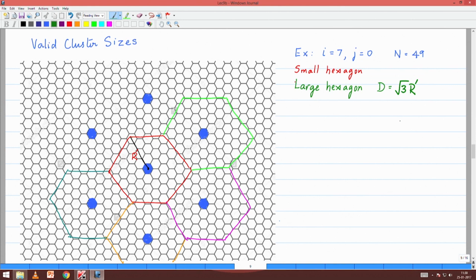That's a valid combination. So basically, along the centers, notice I've gone along the centers. Let me draw it with a different color. I go along the centers. This is cell number 1, 2, 3, 4, 5, 6, 7. And like that I have gone on all 4 sides. Okay, that gives me a location of my co-channel cells.